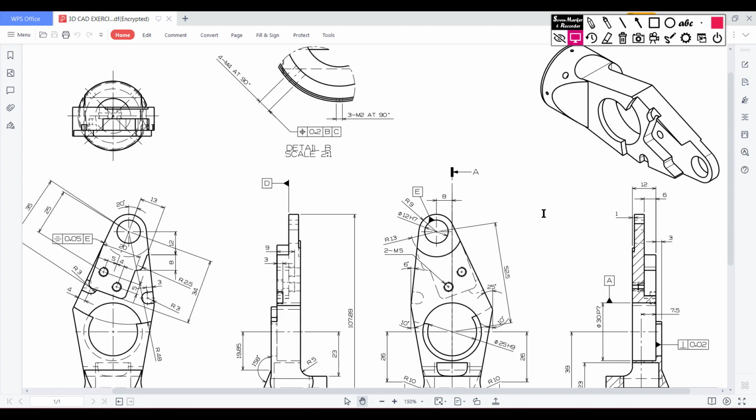So in our sketch, if we see here, we have another circular cut like this one here. Okay, so what is that circular cut? If we look at this sketch, this is our circular cut. This circular cut has a dimension of 48 radius, and its extrude cut is 3 unit. So it has an extrude cut of 3 unit.